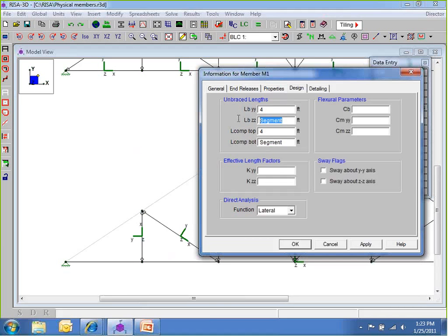So what we've got is I can put segment in. I had mentioned that earlier here, but you can just type in S or segment. And what that means is it's going to go from this node here to this node. It's going to calculate that distance along that segment, and it's going to calculate the distance along every node-to-node location, and that will become a brace point. So segment's a really good tool when you have something where you have to calculate it along the distance here, like on a truss.